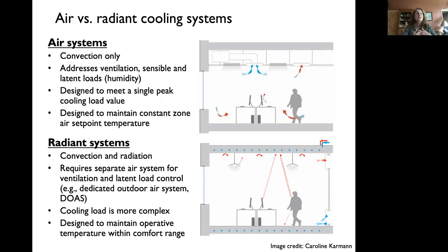The purpose of these is to actually intentionally try to just use air as your metric for saying what it is that makes us comfortable. But we also know from our comfort lecture that we exchange energy with the environment in a variety of ways. We're exchanging energy by convection to the air, but also by radiation to the surrounding surfaces.